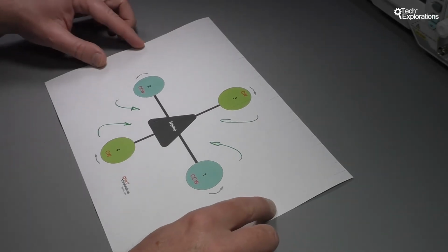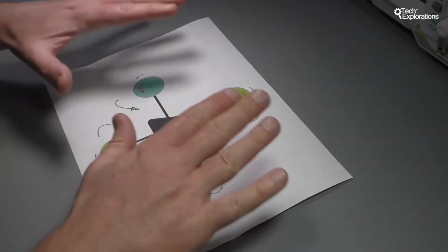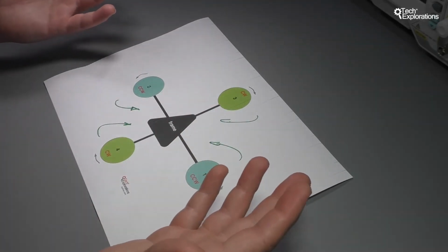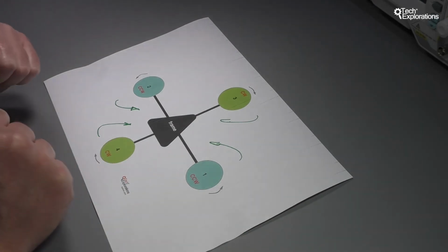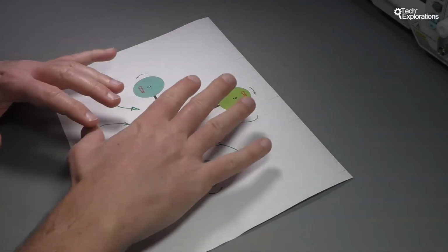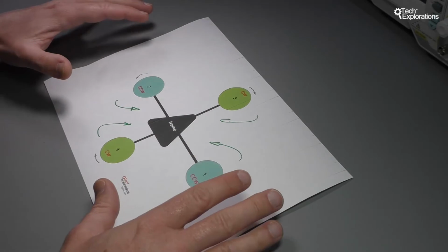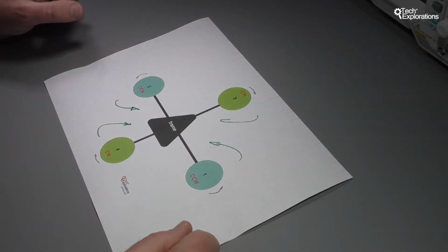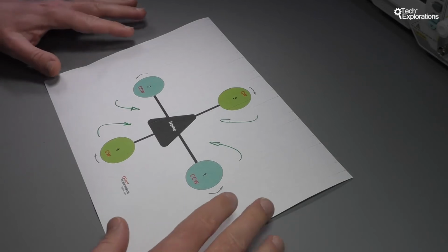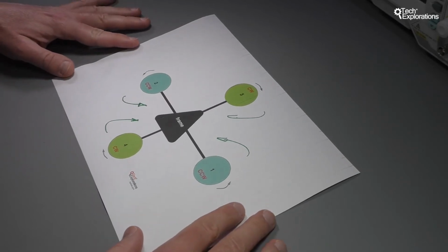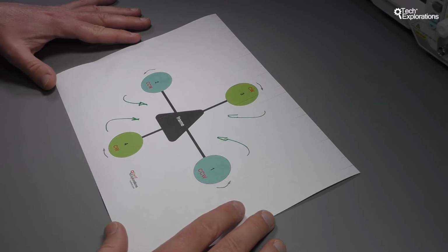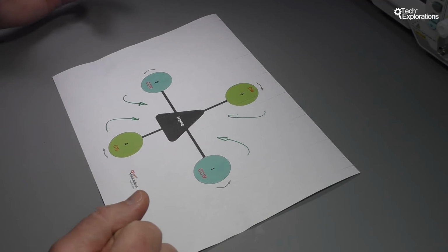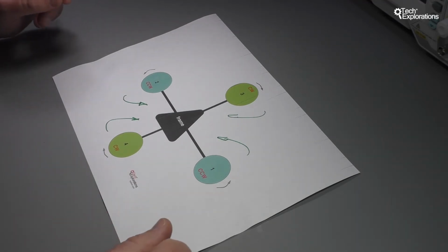So there you go, without having any complicated components, any motors controlling control surfaces like a rudder, for example, that you have in a normal plane, you can control the flight of a quadcopter just by changing the rotational speed of the motors and the propellers that they control. This is a great advantage for quadcopters in particular and for drones in general, and this is one reason why they've become so popular.